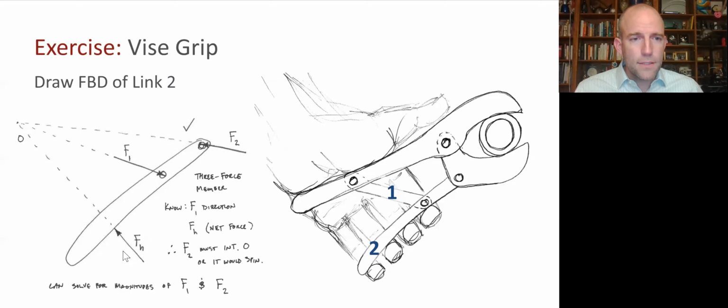You may have indicated this as a distributed force. And you've seen in some other classes that those distributed loads can be helpful for understanding, say, deformation of a beam. And that's really useful in civil engineering things. But here, if we're interested in figuring out what this unknown force is at the next link, then Newton tells us it doesn't matter how this force is distributed as long as we get the total force, the integral of the force, applied at the center of pressure. We'll have an equivalent effect on this if we treat it as a rigid body. So that's how we get to this assumption. And those distributed loads can make the analysis a little more annoying.